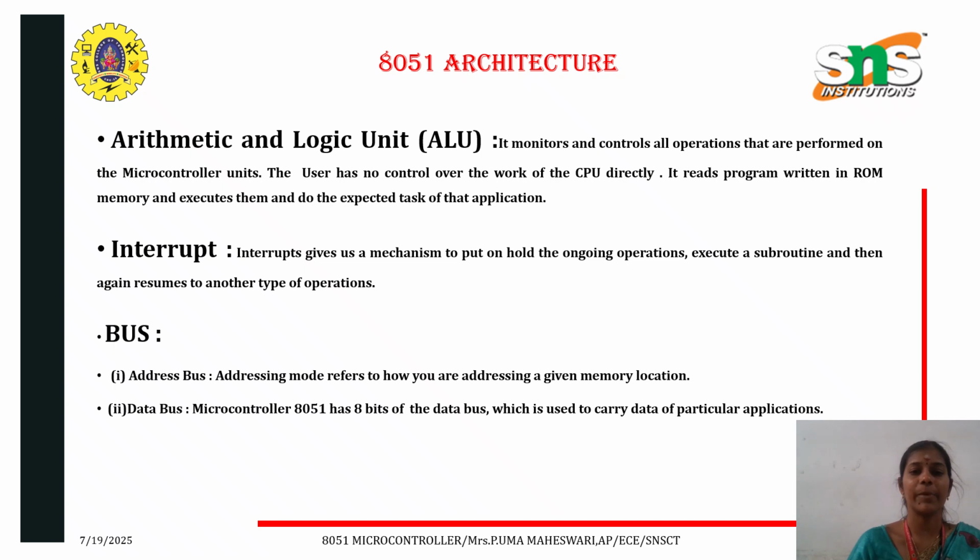The interrupts give a mechanism to put on hold. What does hold mean? It means you push some address onto the stack, and you attend to the interrupt that has come in. You give your concentration there, and then you resume the earlier process, that is, you pop the address and continue your work. This is the main task of an interrupt.